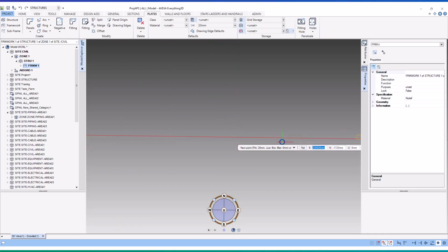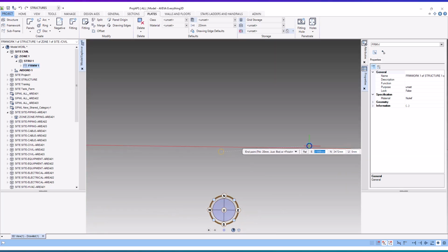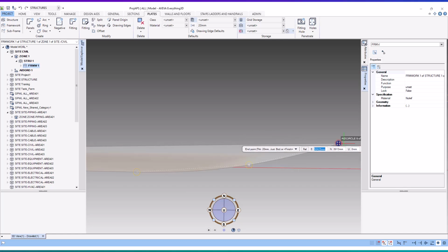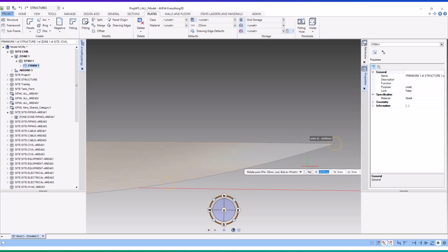If a curved section is required, simply press the down arrow key and choose the arc option. After selecting arc, pick the two corresponding points to define the curved edge. Continue this process until the entire ground boundary has been completed.